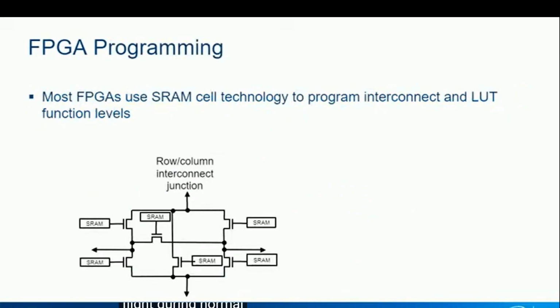With all these different types of architectural structures in an FPGA to configure and control, a lot more programming information is required. Also, to support possible connections between everything while still including a large amount of available user logic, simpler and smaller programming structures are needed. To meet these goals, FPGAs use SRAM cells to program logic levels and make routing connections.